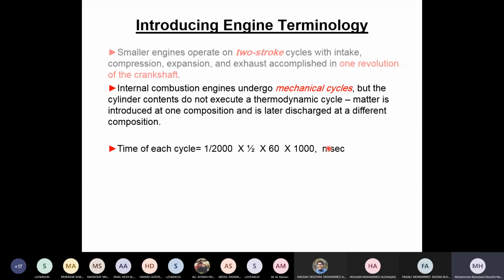So this is a figure that you can calculate for your car. I did not get anything from mine here. This is the revolutions per minute, and from this you can calculate the time of the cycle, and then of course you can get the time of the stroke and so on. So I want you to do this exercise so you have more depth of feeling for the engine.